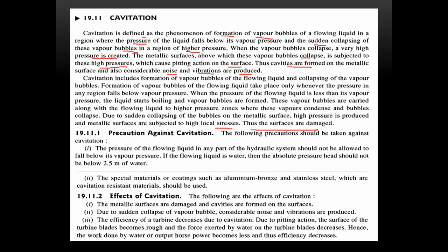So whenever the cavitation forms, what happens? Surface మీద stresses అనేది ఎక్కువ form అవుతుంది. So whenever the surface is getting stressed, automatically the veins will get damaged. Veins damage అయినప్పుడు replace చేయాల్సి వస్తుంది. Thereby the efficiency of the centrifugal pump will also decrease.